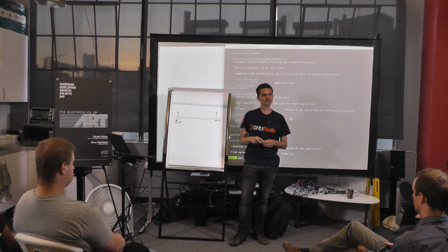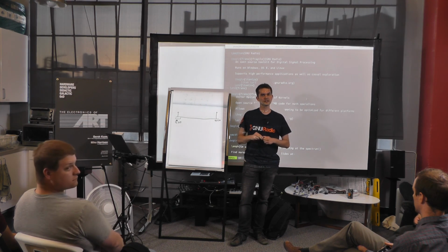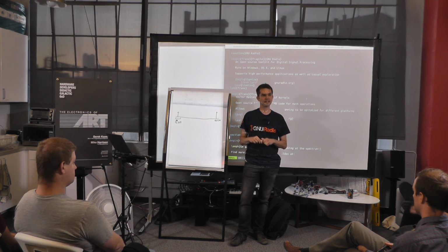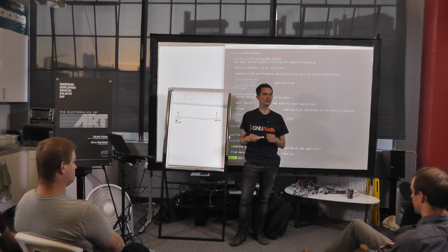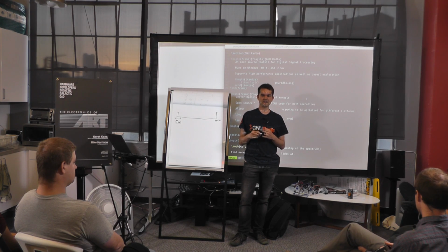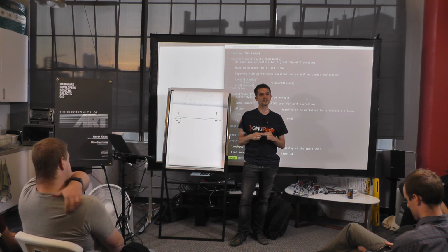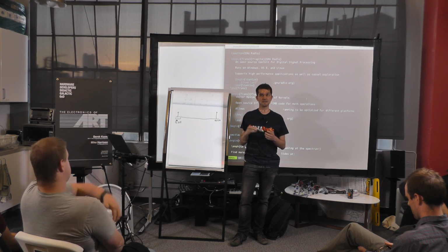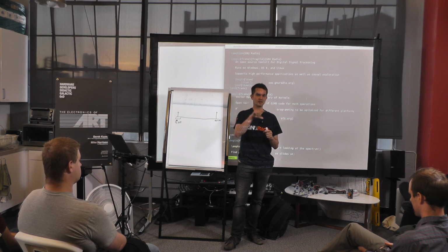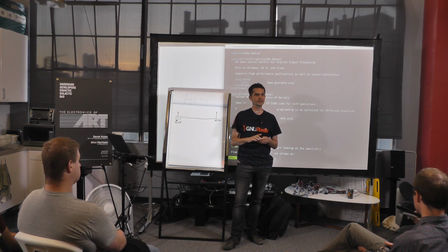So part of your software defining is that down mixing? So the radio, that is basically the only responsibility of the radio, is to do that down mixing. Maybe a little bit of filtering depending on which one you get. And then the B200 has an FPGA, and the BladeRF has an FPGA on it, and possibly the LimeSDR, I forget, have FPGAs on them, and they have a small amount of digital signal processing built in.